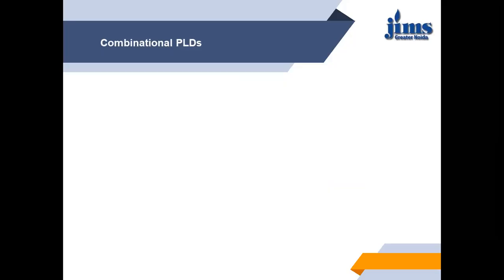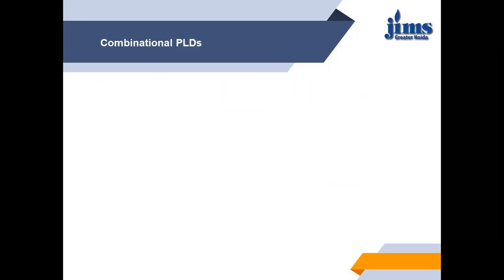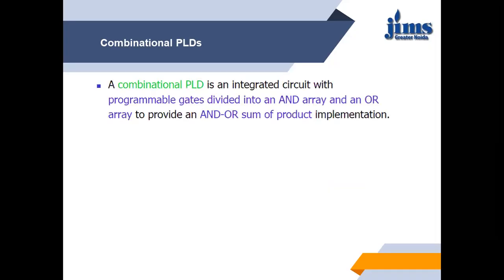Now come to the combinational programmable logic devices. There will be a question from the PLDs in your exam, and the question will be of about 10 marks. A combinational programmable logic device is an integrated circuit with programmable gates divided into an AND array and an OR array to provide an AND-OR, or sum of products, implementation.